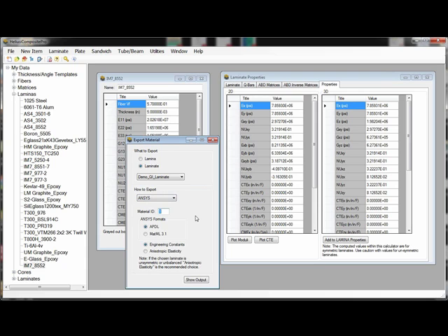In ANSYS, we have the ability to export material data for both the classic ANSYS APDL or the newer MatML 3.1 format that is able to be imported into ANSYS Workbench. And for Nastran, we have multiple ways of exporting this material data available as different material cards for use in a Nastran input file.